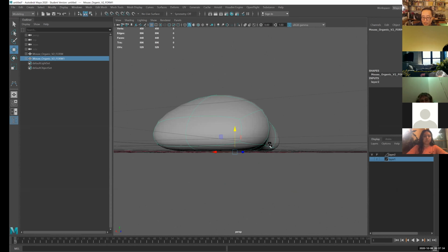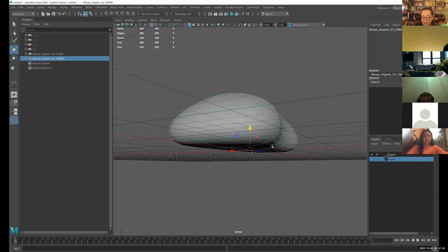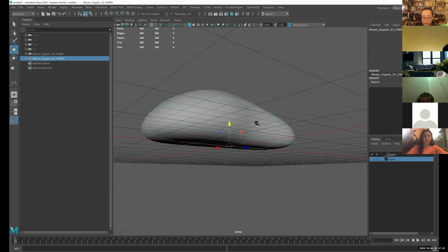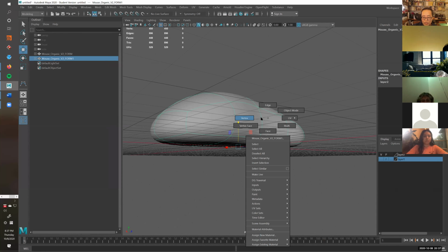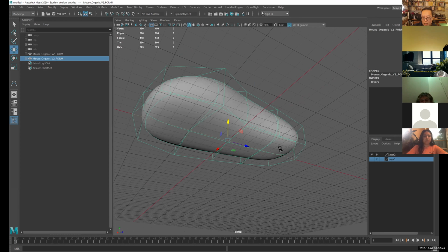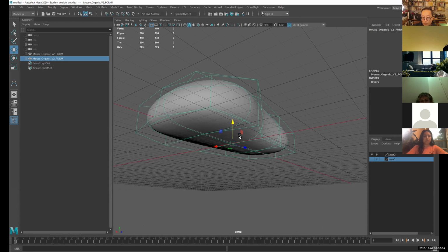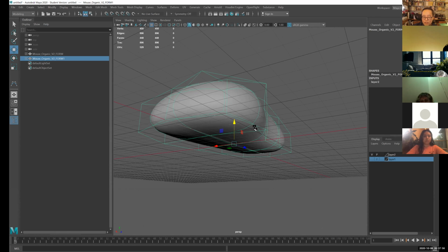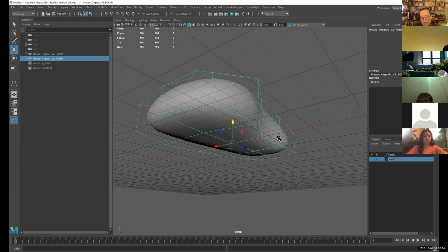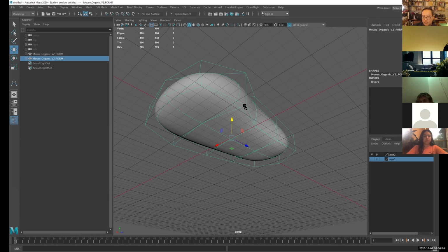On the bottom here, these are probably a little bit too round. Maybe I need a little more flatness in the bottom and then come up. You can do several things with that. If you look at the geometry, there are these edges along the bottom here. You can either do something like a bevel to double up on these edges so that it holds the form better and gives you an accented edge, or you can take these edges and put a crease operation on them. Either one is okay at this point because it's at concept level. So I'll show you both.